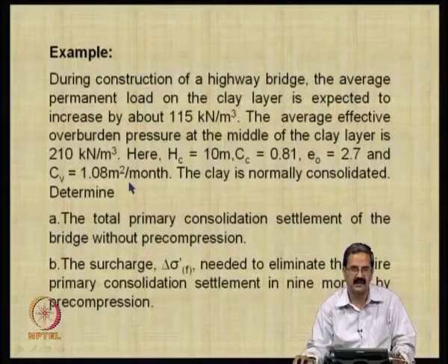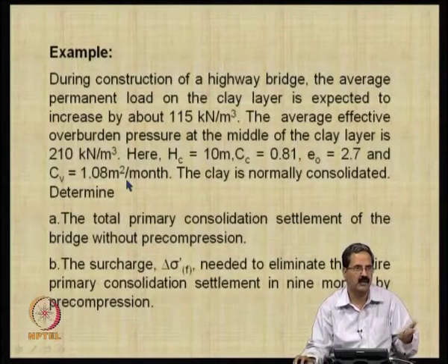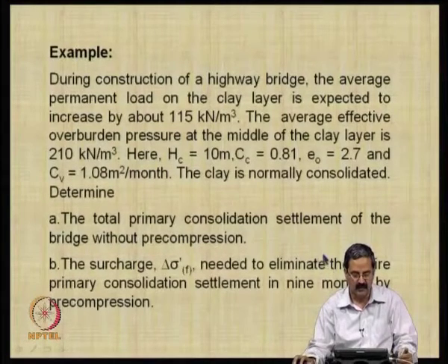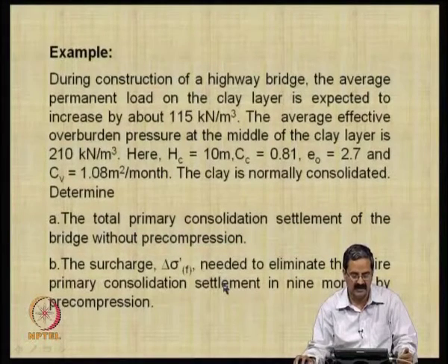We are trying to discuss in terms of months, because you have to just convert what you get in the laboratory, normally in seconds or minutes, into months, because we are more comfortable with construction times. So, we will try to calculate what is the total primary consolidation settlement without pre-compression, and how much surcharge you need to apply.